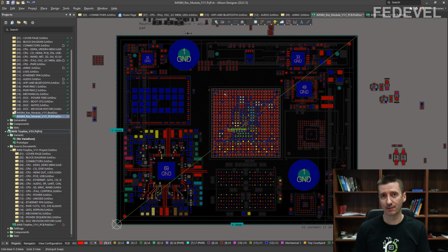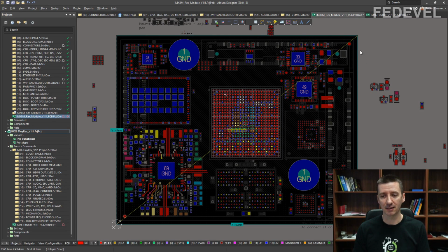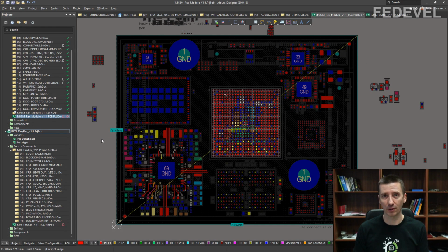the price increase, if I decide to use via in pad in this board, is not going to be huge, and it is a really good opportunity to test this via in pad technology. So for example, in future, if I really need it, I will exactly know how to use it in other boards.